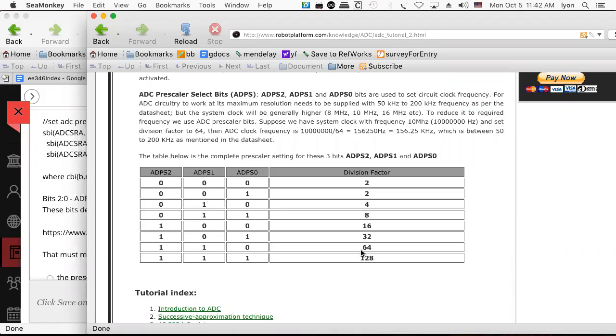So then if you inverted it, that is to say, raise it to the -1 power, you get 8 times 10 to the -6, which is 8 microseconds. That is a period of time which is not equal to your sample rate, right? It sounds like it should be, but it isn't. This is not the sample rate. What this is, because it's a successive approximation ADC converter, is the clock that goes into the register for the conversion. So it's not quite your sample rate yet. It's the clock rate that goes into the ADC converter.